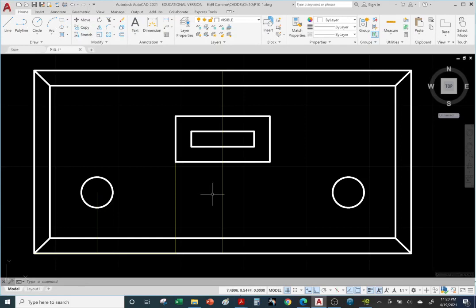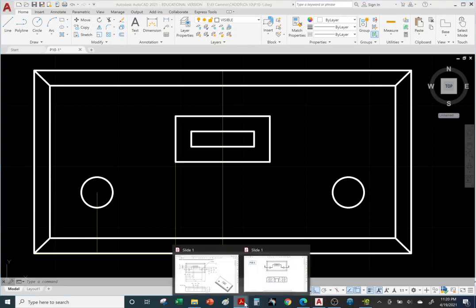Okay, so we do need green center lines, but our cutting plane is going to overlap the green center lines, which is actually normal. It happens quite often where our cutting plane will overlap a center line. So we tend to allow the cutting plane line to override the center line, and leave out that center line in that area where it's being overridden by the cutting plane line. All right, so let's go to the answer key.